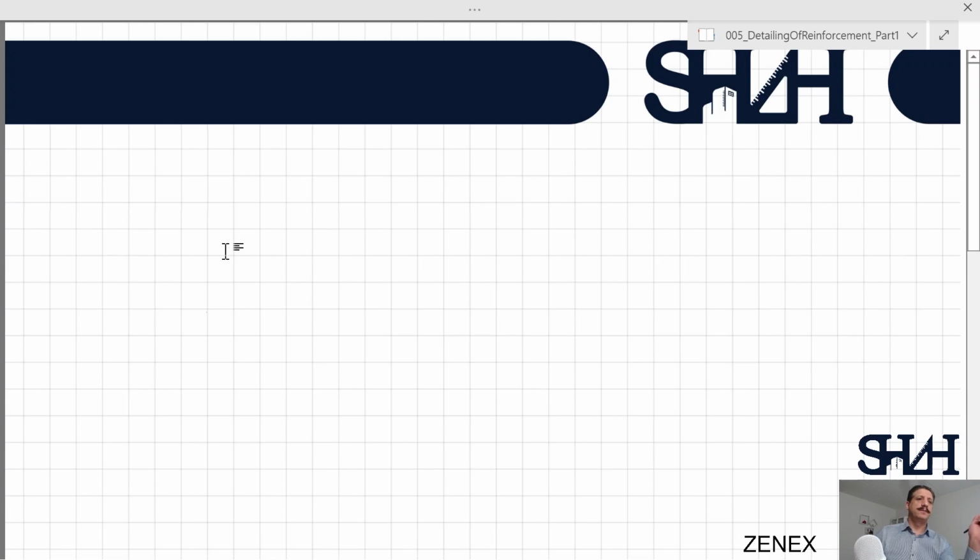The first step for the design of a concrete element is to have a simple dimension. For example, you want to have a 6 meter beam, and then you need to know the required depth of the beam. That is not given in chapter 9, it is given in chapter 7, and the minimum requirement in this chapter is due to serviceability and, for example, checking the deflection.